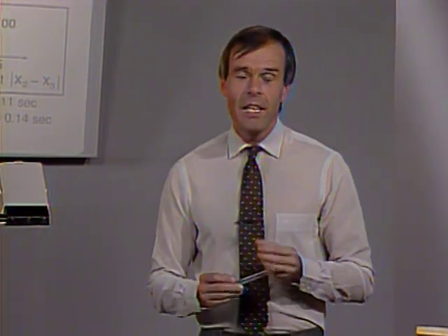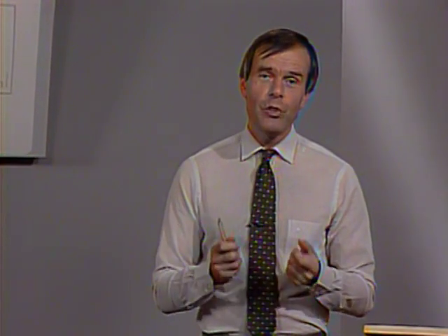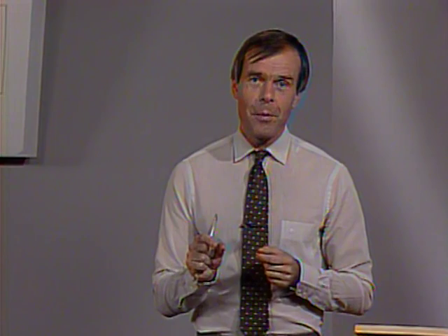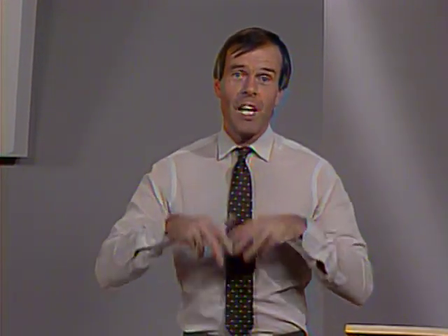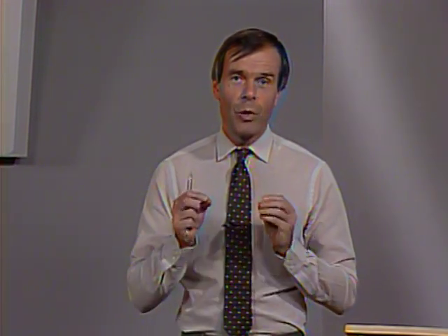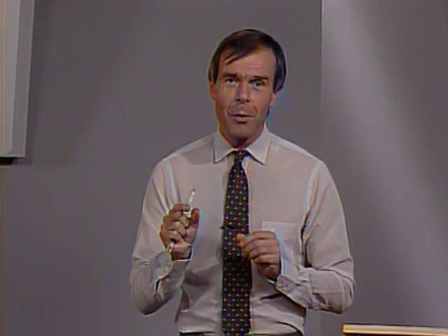You see, in linear analysis, when you use the central difference method with a time step that is larger than the critical time step, you will, after a few time step integrations, see that the response becomes very large and the instability is obvious. The instability is really obvious when you apply the central difference method with a time step that is larger than the critical time step to the solution of the system.